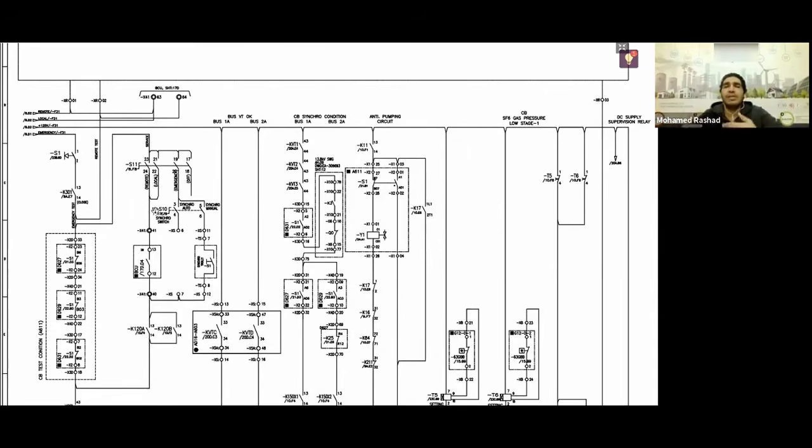I'm talking about an emergency in the sense that you don't know how to close from the PCU, from the SCADA, or from the remote. So you come to the station and use the station itself, because now all the stations have become automated. Ideally, you should close through the computer screens available in the substation automation system or in the SCADA system, okay? The difference between it and the local is that the local closure is done through the PCU itself. In the past, this closure was done through the control room, but now it's done through the PCU located in the same cell. This means that you are present in front of the cell itself. So currently, there is no difference because the PCU is in the same cell.